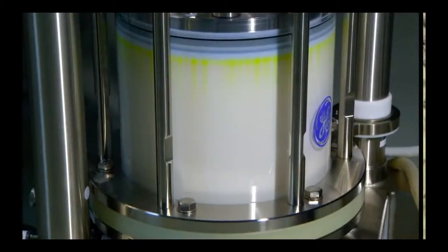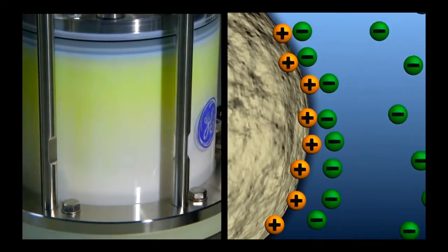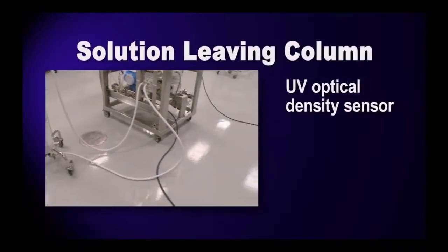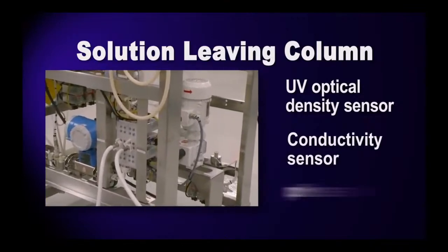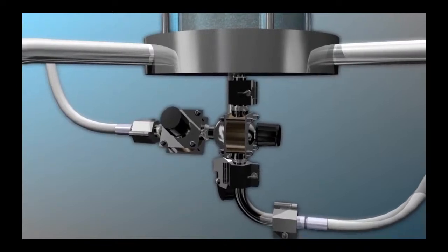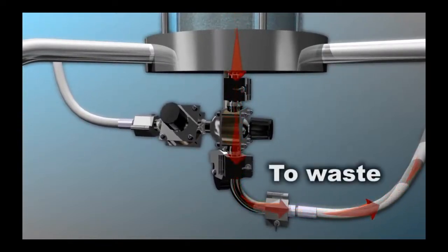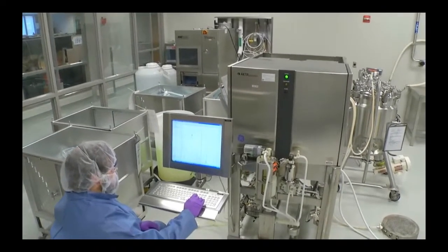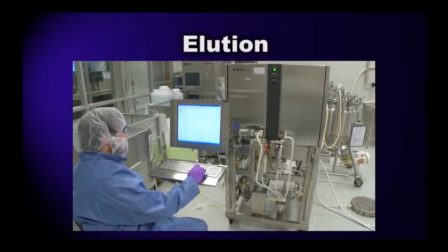Then, as the lysate passes over the resin beads, the negatively charged protein binds to the positively charged beads. The solution leaving the column passes a UV optical density sensor, a conductivity sensor, and a pH sensor. The optical density sensor's low readings confirm that the GFP is not in the solution, so the outlet valve sends the solution to waste. When all the lysate has entered the column, or when the capacity of the beads to bind the protein has been reached, it's time for elution.